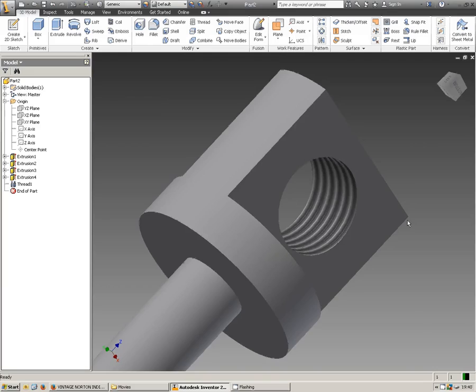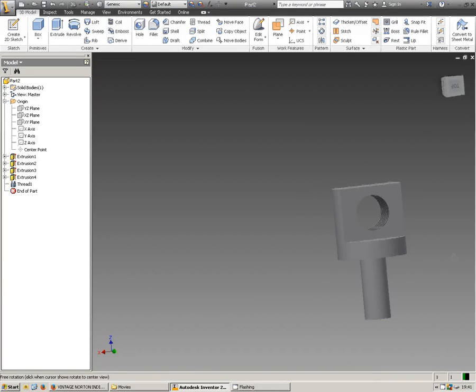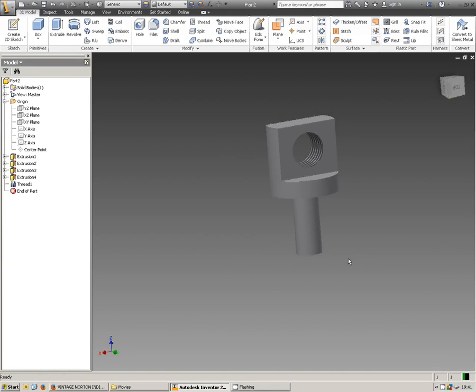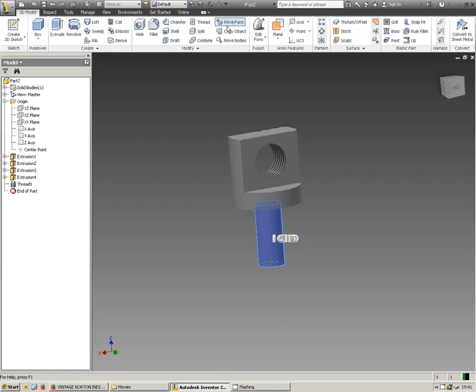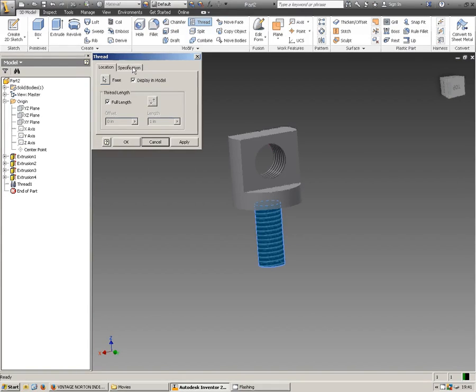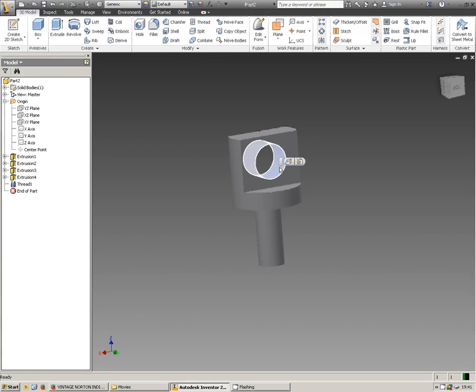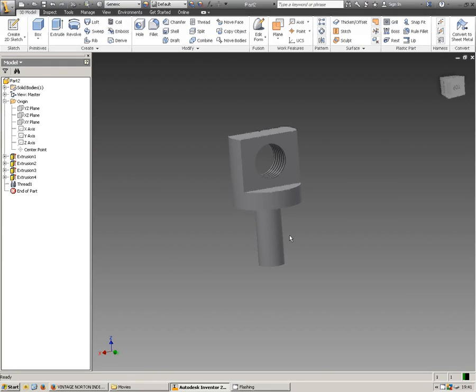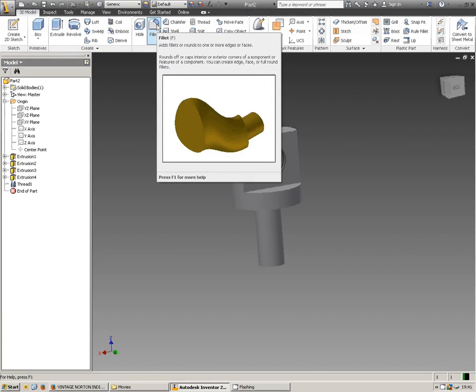sure of yet. Finally, the other thing I want to do is to also thread the outer cylinder. So I'll just select that, and I'll select thread and specification, and I'll just go for the same size again. Why is that the same size? Cancel. What was that there? That was edit thread specification 1/2 inch 16 UN. I'll make that the same, although it should be 3/8 BSF.